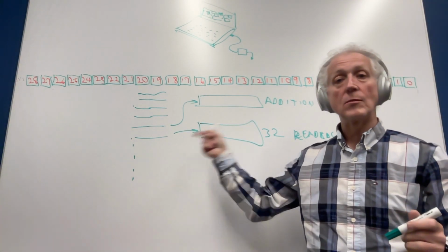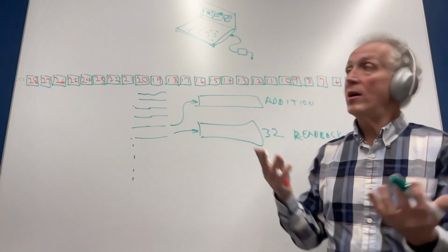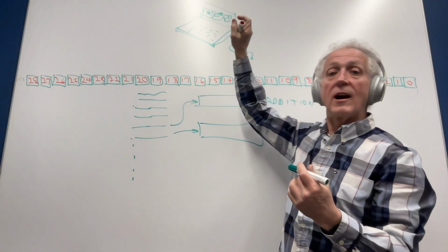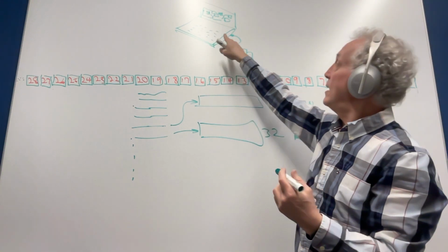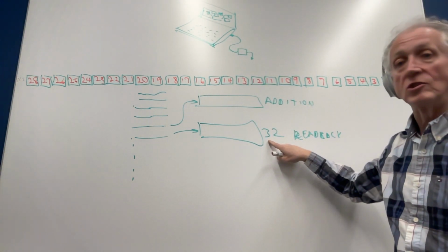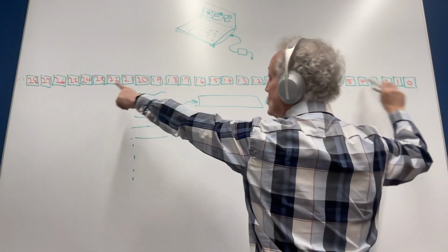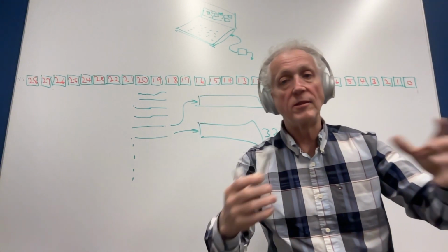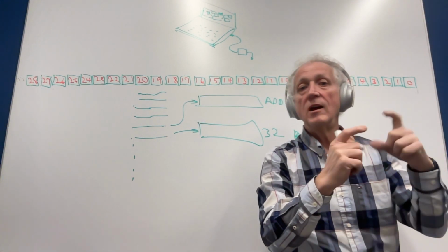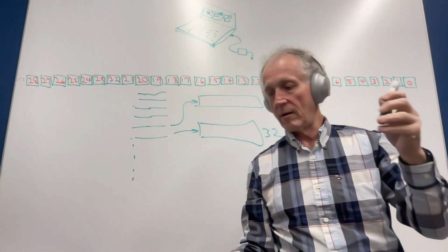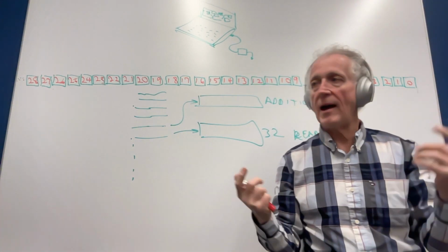And then at any point, via the USB-I, you can go into Sigma Studio and click on the read button. It will ask what's stored in this memory location, take the 32 bits, bring it up and display it for you on the screen in a little readback box in hex or in a fixed point format.